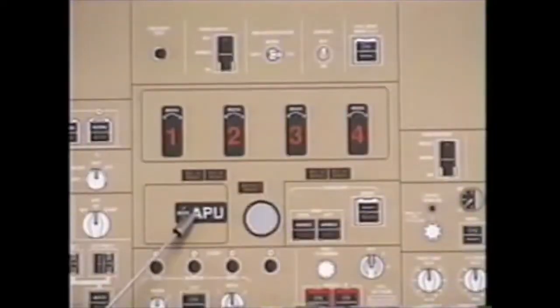In addition to the cockpit indication of the APU fire warning, externally in the right body wheel well or right aft wheel well is a remote shutdown panel for the APU. This remote shutdown panel contains a stop button, a fire control handle, a continuous horn, and a red light. The horn will sound continuously and the light will illuminate during an APU fire warning and an APU fire test.